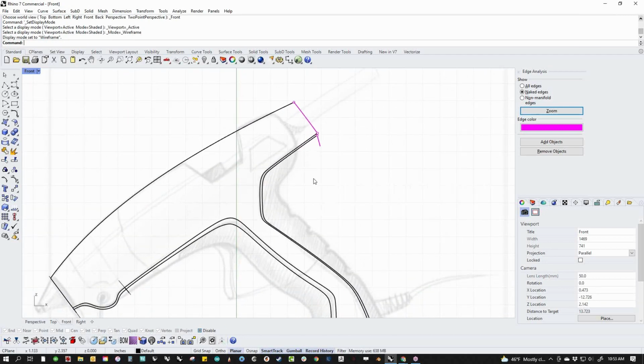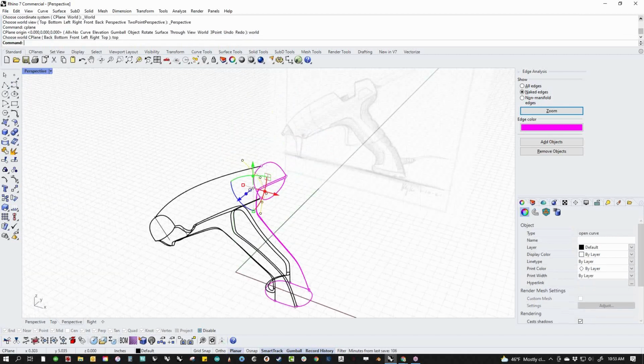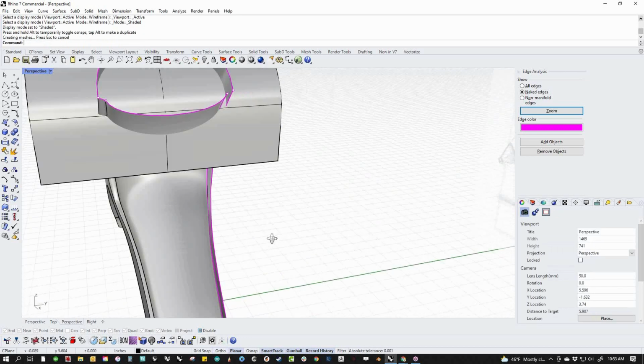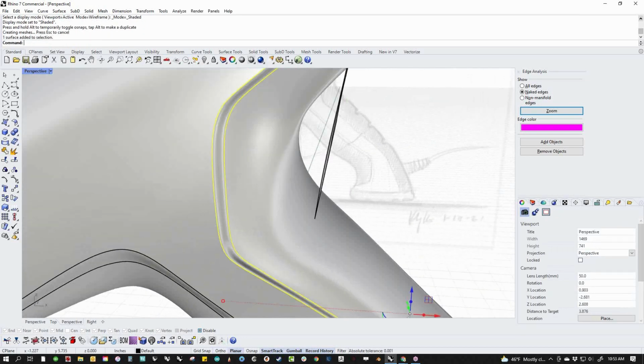And then we need to clean up this back here. So let's draw something vaguely in that neighborhood, something kind of like that. And let's overbuild it instead of just trimming. I'm going to drag the extrude dot off this curve, and I'm going to hold down Shift, which makes it go in both directions. And it looks like I'm missing my fillet on that side.